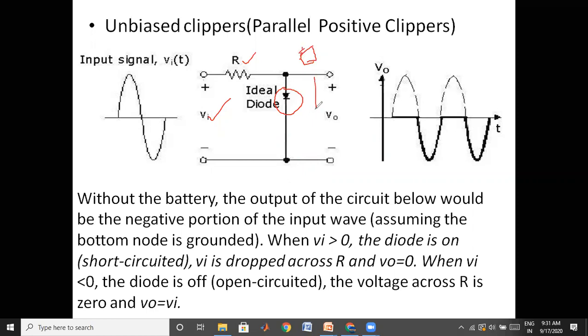The actual output will be here. This is your load resistance RL, and the other one is not the load resistance. Previously we wouldn't find this resistance, because the diode was in series. Now if you make a short circuit, the load is also short circuited, because the current finds the shortest low resistance path. Total current will flow through this diode and the diode gets damaged.